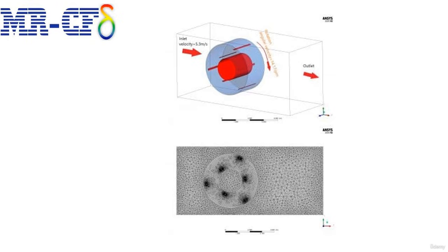Geometry of the fluid domain is designed in Design Modeler and the computational grid is generated using Ansys Meshing. Mesh type is unstructured and the element number is 1,546,624.